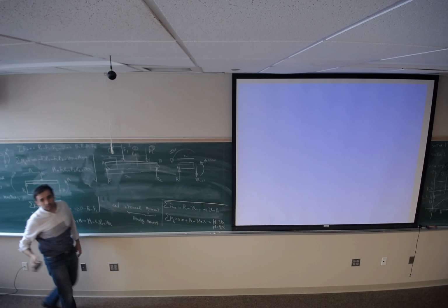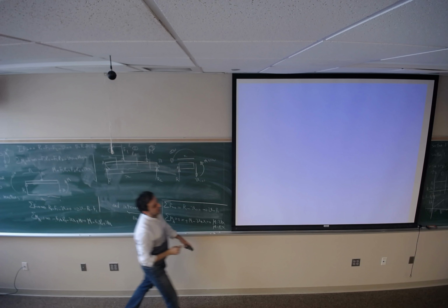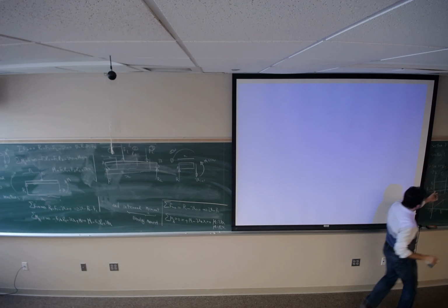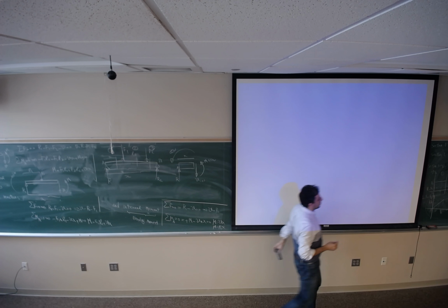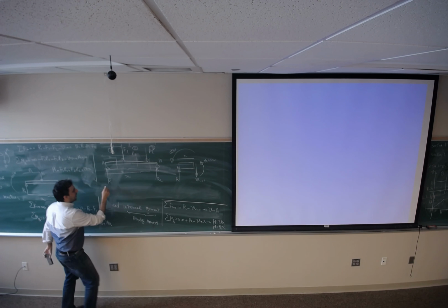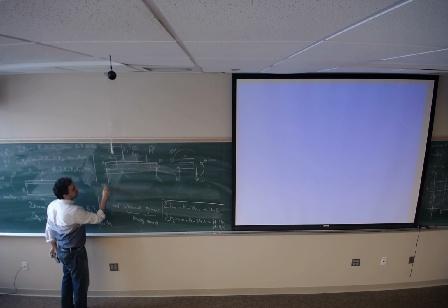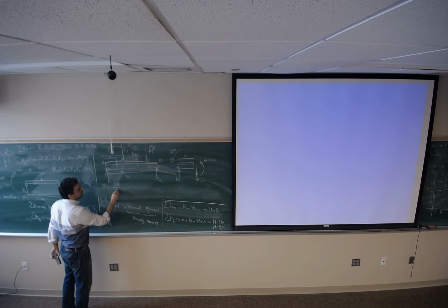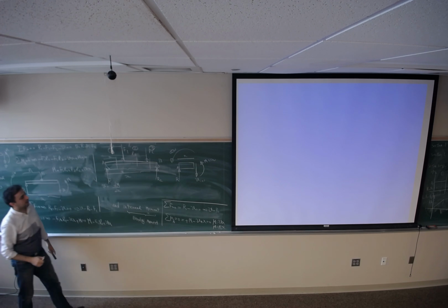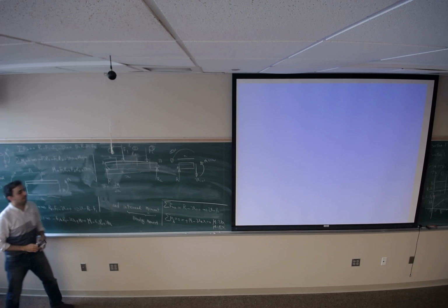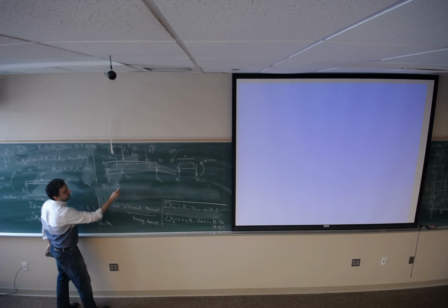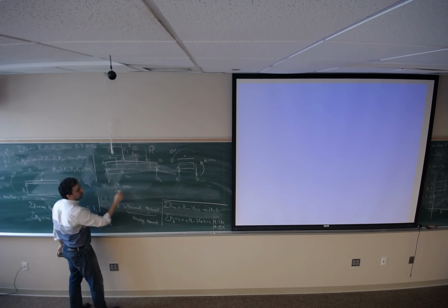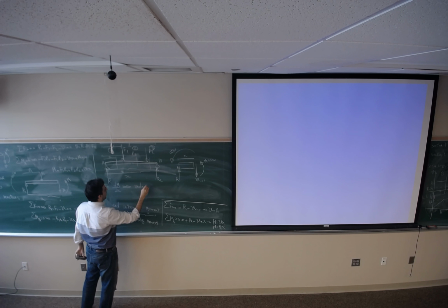Any question on this? Before I go through one example, there is another thing that I should review from that course. V, shear force, we can have this correlation between V and M. V is the derivative of M, the bending moment, with respect to x. If I multiply both sides, V dx equals dM.